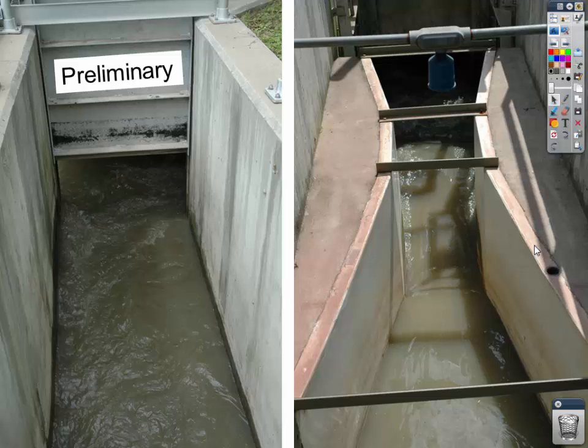So it's very smelly. By the time it comes out of these pipes and hits preliminary treatment, it's first hitting the air, and that's where you get that really terrible smell of the sewage treatment plant. A lot of people think it's somewhere else along this path of treatment, but it's not. It's right here when we get in. Those of you who are going on our field trip to the Telford wastewater plant, we will walk over this area and you'll see it and you'll smell it. But this is preliminary treatment.